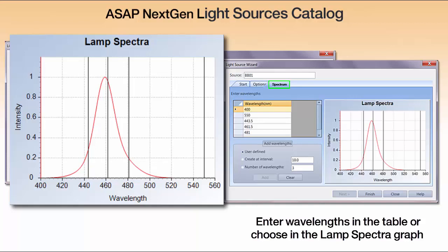The process for creating a source when we start with it for the first time is we actually create ray sets, and that's where we choose the options for the wavelengths at which we model. ASAP models sources at discrete wavelengths. We don't have a continuous spectrum model, but you can make the spectrum essentially as dense as you like, as long as you keep the number of sources below a system maximum. And you can always do a nonlinear analysis by doing a spectral band and then adding another spectral band in a series of analyses. And we can graphically choose the wavelengths when we have the spectrum showing in a case like this, or we can type them in.